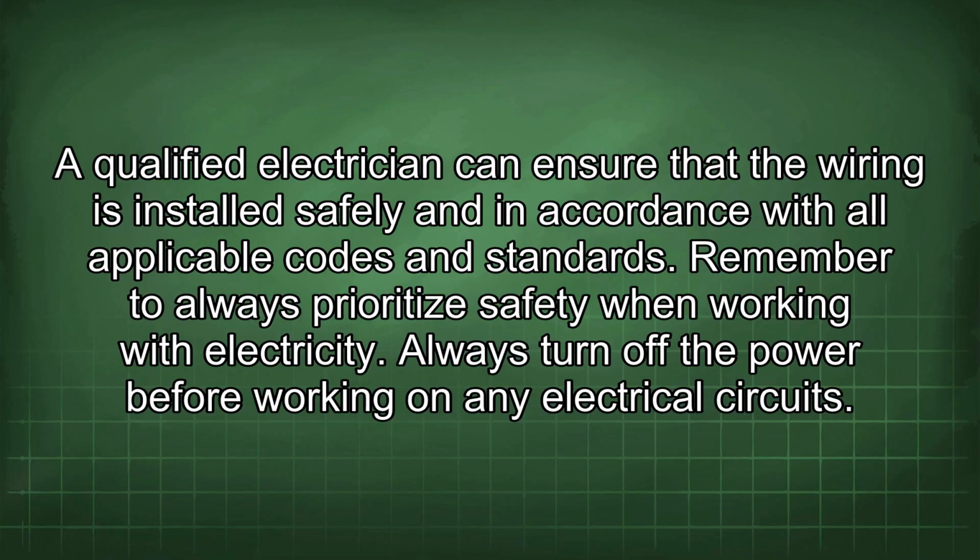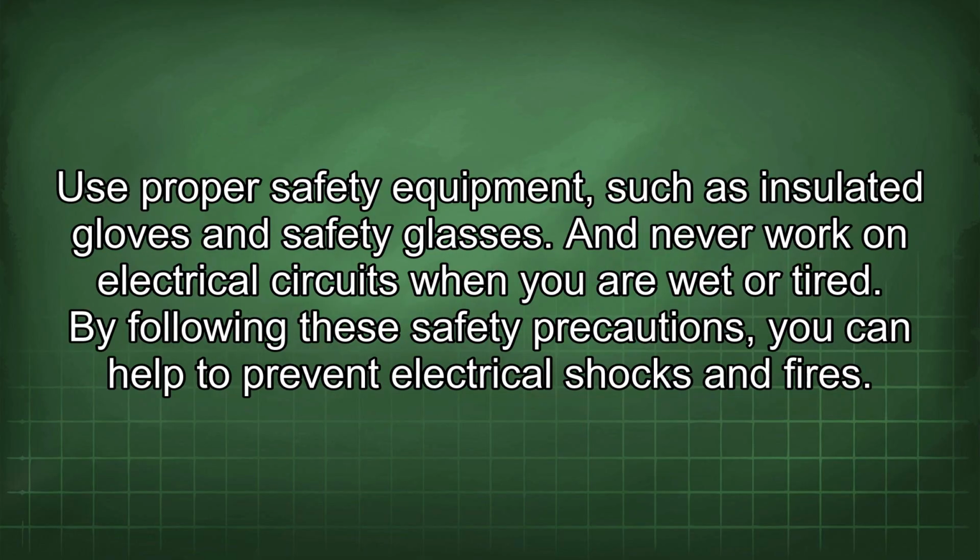Remember to always prioritize safety when working with electricity. Always turn off the power before working on any electrical circuits. Use proper safety equipment, such as insulated gloves and safety glasses. And never work on electrical circuits when you are wet or tired. By following these safety precautions, you can help to prevent electrical shocks and fires.